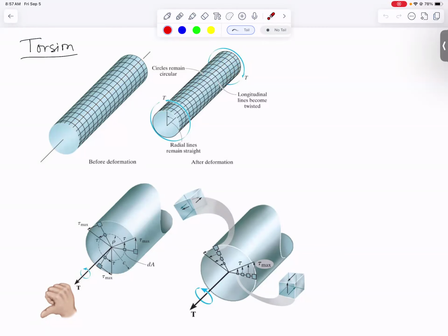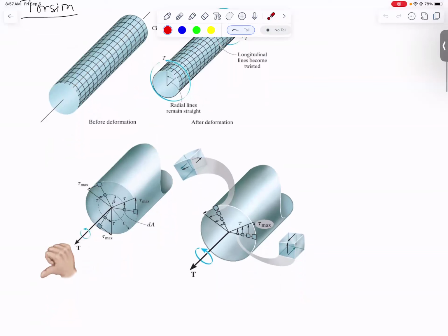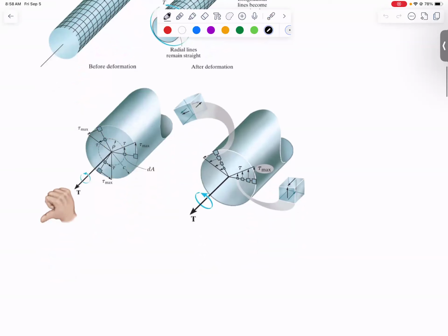Today we are going to talk about stress. The idea is that if you imagine your torque going around the circle like that, I'm going to draw a quick 2D picture to go along with this. If we have a circular shaft, we have a torque in this direction. They're showing you that a torque in that direction, if you use your right hand, would have your thumb coming out, so the torque vector is pointed in this direction. We're going to define that as positive internal torque.